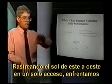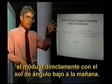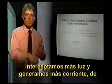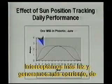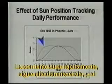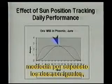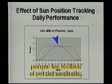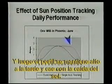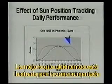By tracking the sun east to west in a single axis, we face the low-angled sun in the morning directly with the module. So we're intercepting more light, we generate more current. So at the same time in the morning, we're able to generate much more current. The current value rises quickly, stays high during the day. In the middle of the day, of course, the two are the same because they're both facing noontime sun. And then the profile stays high in the afternoon and finally falls off with the setting sun. The enhancement that we get is illustrated by the increased area on either side of the curve.